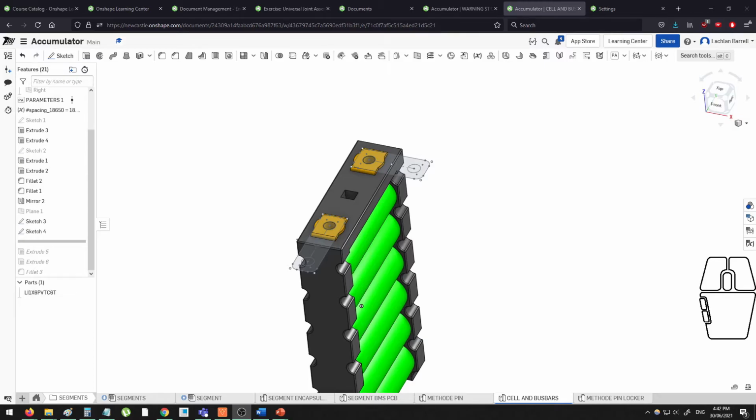So to use a variable in Onshape, all you have to do is select the variable tool up here in the Part Studio. I can set that to be something called copper bus bar thickness. You can choose whatever name you want here, and then I can set it to be 4mm. So obviously the units matter down here. It's related to these up here, but I'm sure you'd know that from watching the learning pathways.